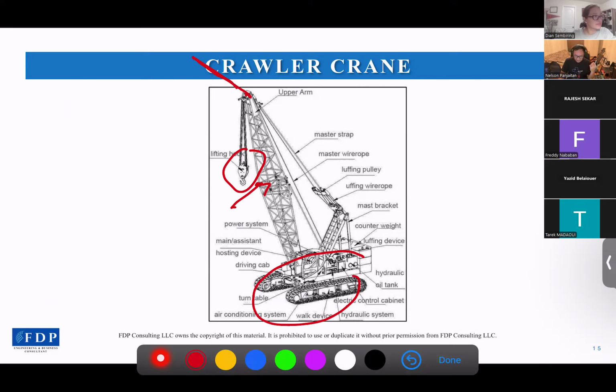And then the next one is the counterweight here. This component is important to keep our crane COG in a balanced position. Some cranes also have an additional counterweight behind, called the superlift counterweight. So the superlift will usually be here.